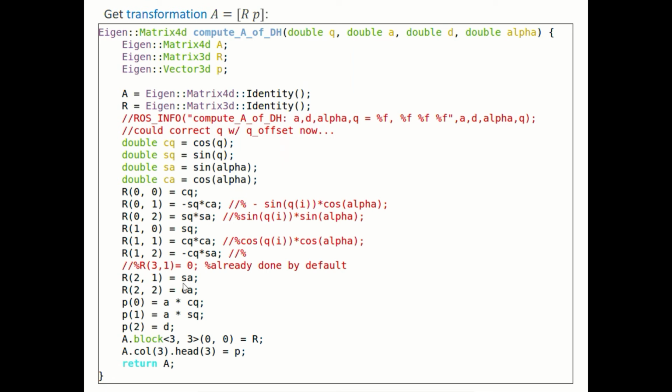And so here we have, let's see, oh, sorry, this is going down the columns. Now, if you feel confused about these values, you need to go back and study DH parameter conventions. Okay, these are just rotation matrices with some assumptions. This is going down the column 1, column 2, and then column 3. I think this should be 2, 0, 2, 1, 2, 2. It would be best to draw it out to get here.